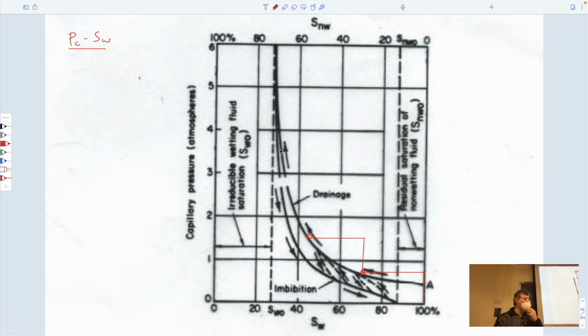These were first developed in agronomy. So if you have soil in a crop, you drain the water out of it. You talk about draining water, you don't typically talk about draining air, right? And so that's the reason for that. So if we point out the features of this curve, let me highlight each of them in due course. The drainage curve occurs when you push air into the system. You slowly, at the detriment of air, push out water.